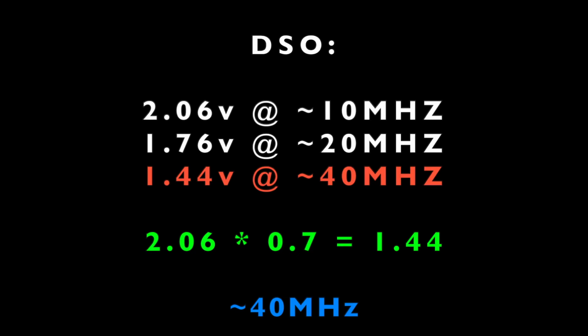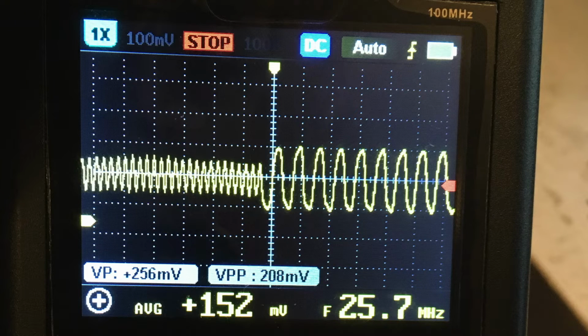I would like ultimately to properly test the bandwidth at each of the variable settings that changes the sample rate, rather than just giving some big blanket statement, because that's misleading depending on what you're trying to measure. And looking at the shape of the 20 megahertz signal, it seems to me that we have something a little bit higher than 40, definitely, because of the shape, or maybe there's some automagical trickery going on in there. It's really tough to tell, and without the firmware I can't know for sure. I could just run sweeps into it and then see what I can see at a particular setting.